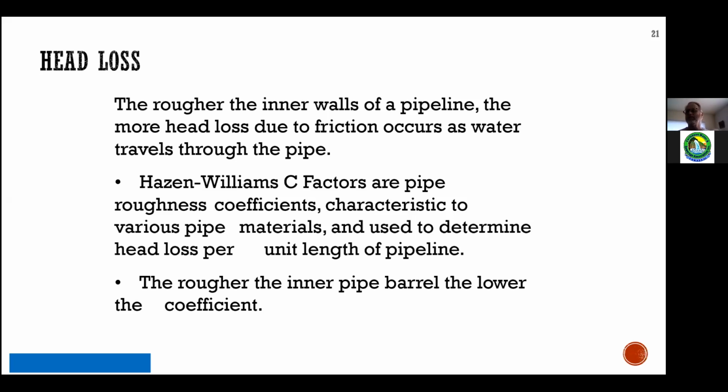So in many ways, the rougher the pipe, the lower the number. I've seen old cast iron that we did flow measurements on, and it really had a C factor of about 36, 37, which is terrible. Cast iron, when it was brand new, put in the ground 80 years ago, would have been at 100. So it's not just that you don't get good, aesthetically pleasing water, it's hydraulically no longer acceptable.